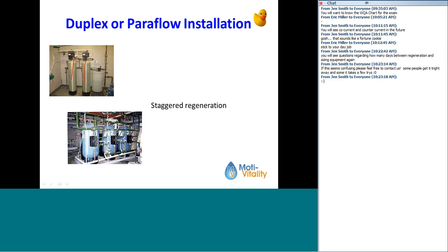Most of your residential softeners out there will give you surface flow rates. Now, through the valve, you can get a heck of a lot more water, but you add resin to it, and now you're restricting the flow of the water. So most of them, even the high flow ones, are going to give you 12 to 14 gallons a minute, which is plenty for most people. But if you've got these high flow faucets that require 21, 22 gallons a minute to run, then you need more. You can't restrict the flow like that.